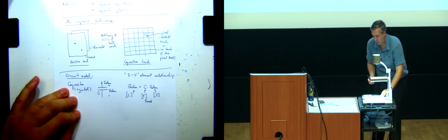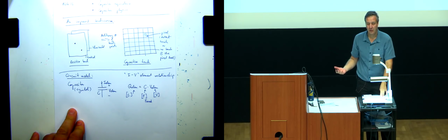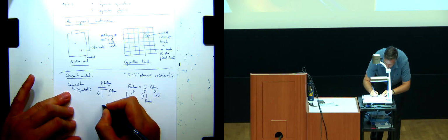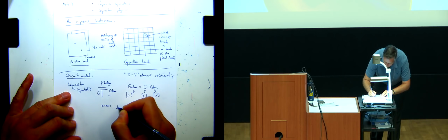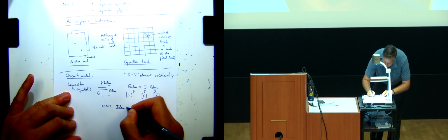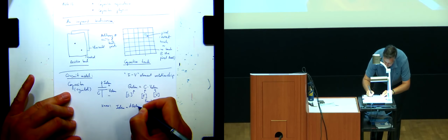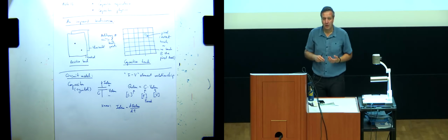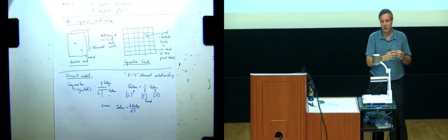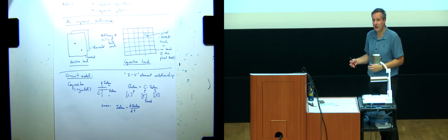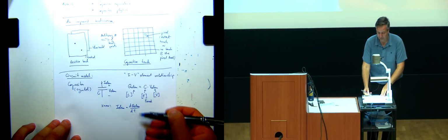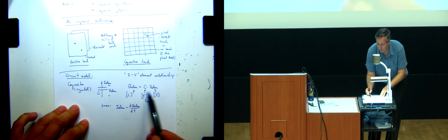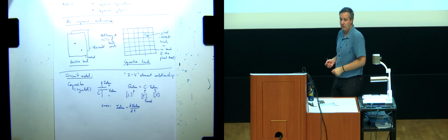Okay, so from here, we can just do a simple derivation to link charge to current, right? We already know that I element is equal to the dq element over dt, right? That's just a definition of current. Current is a certain amount of charge going through some cross-section in a certain amount of time, right? So that's all there is to this. But now we can apply this formula for charge on a capacitor to that current equation.